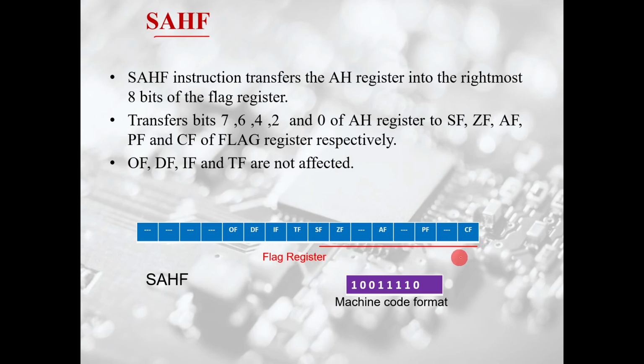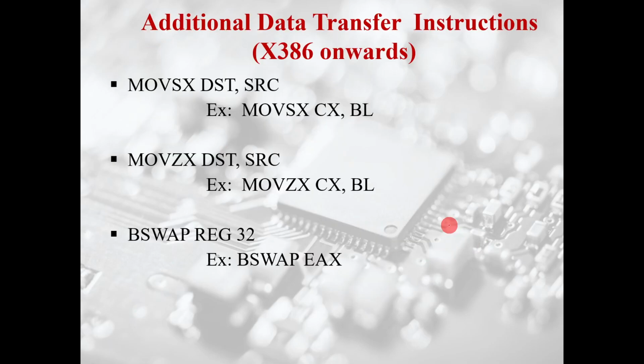Or temporarily I have taken some data from the flag register to the AH register, and from AH you want to put it into some memory also, you can put it there, and subsequently again you want to bring back the original data into the flag register. You can again get it from that memory to AH, and then from AH you can get it back here. So this is what SAHF stands for, right?